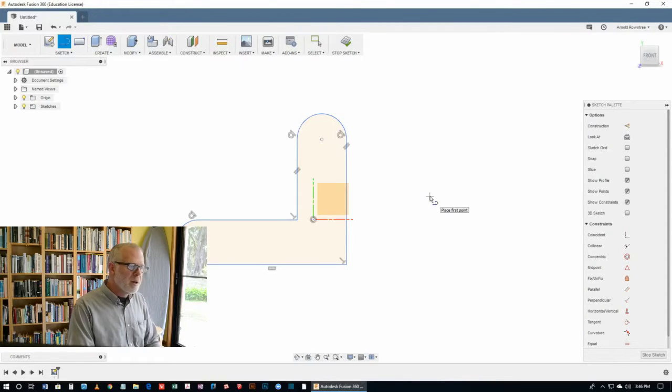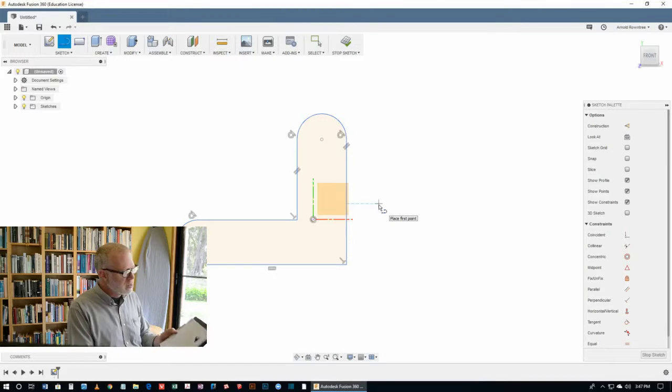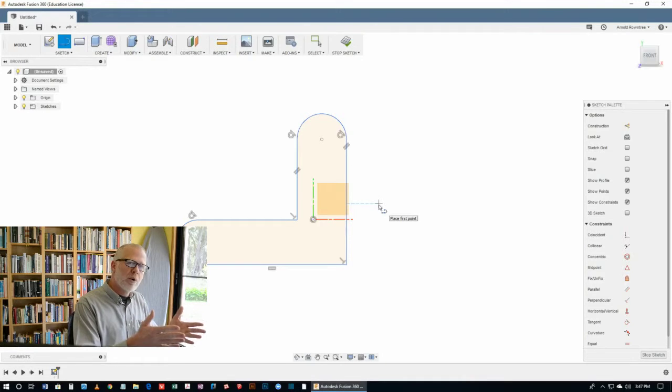You're getting a little bit of an idea of the strategy for producing these simple shapes. What we want to do is begin to use the point of origin and the planes, those reference planes, to help us as we go about modelling. It's not so important with something as basic as this, but when we get to some of these more interesting shapes, it's going to be a bit of an advantage to have that point of origin and those reference planes in a place that's going to help us. So we'll start to take note of that now.